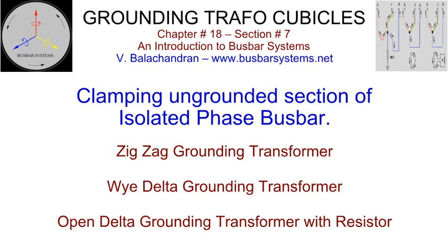Any equipment installed in the generator connection must be highly reliable and it should be ensured that the probability of the occurrence of a phase-to-phase fault is minimal. Consequently, each phase of the grounding device must preferably be separately accommodated in a housing and the secondary connections are made externally. This will eliminate phase-to-phase fault in the generator connection. This is not practical in case of a zigzag transformer. Single-phase transformers can be installed in individual compartments of the surge protection voltage transformer cubicle and the resistor can be installed in a separate compartment in the middle phase.